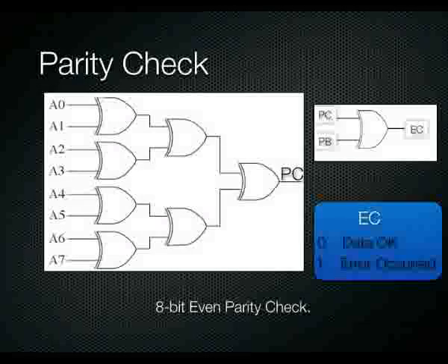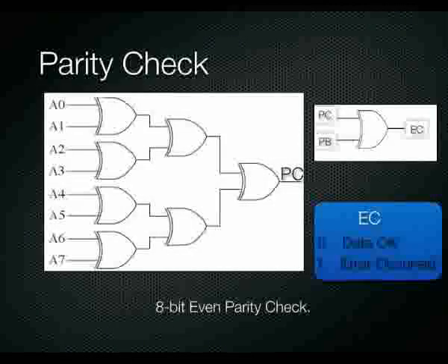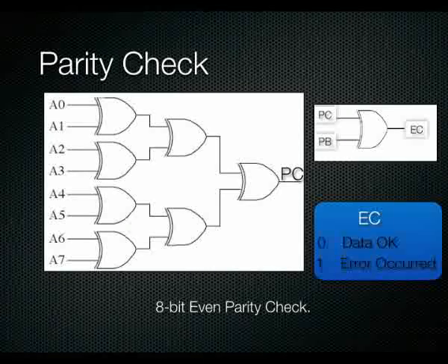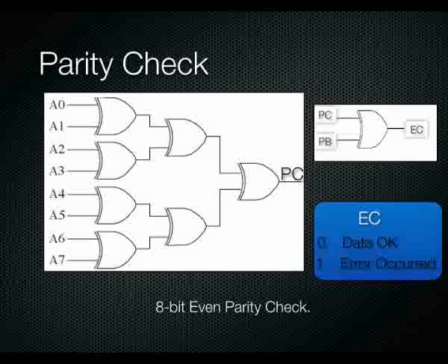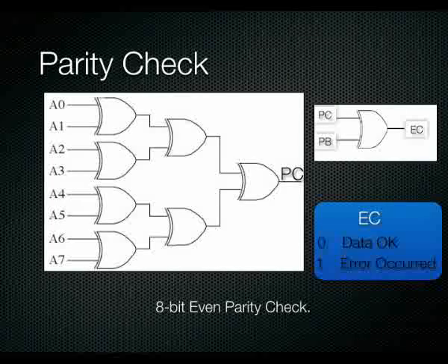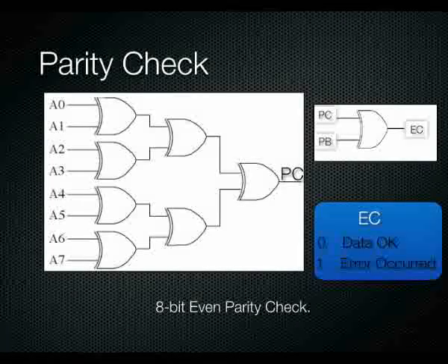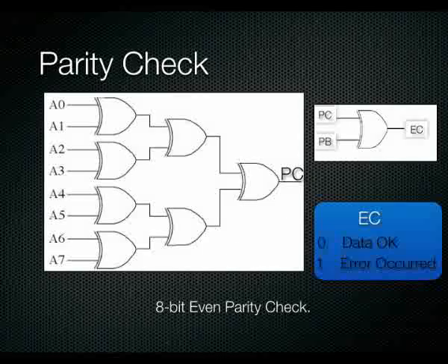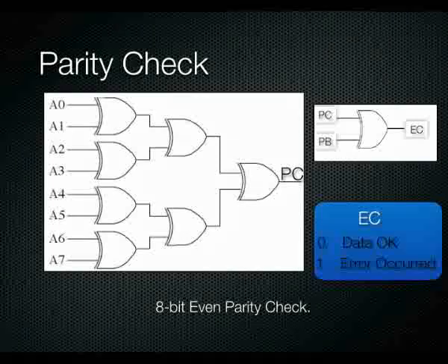So when it comes to checking the parity, and this is where parity, I guess, is useful because it's a very simple error checking mechanism, we might generate a parity for an 8-bit number and ship it across long distances to some receiver down the track, which is obviously separated by some sort of distance. When we get down to that receiver, we generate the parity locally at that end, and then we can compare the two to make sure the parities are the same. If they're not, then we know an error took place.